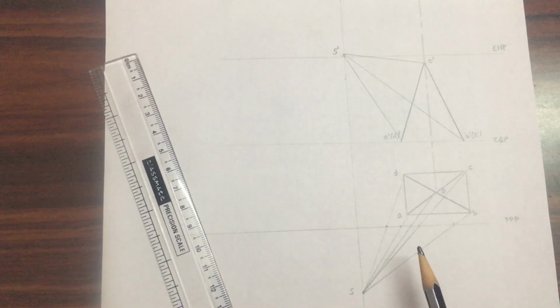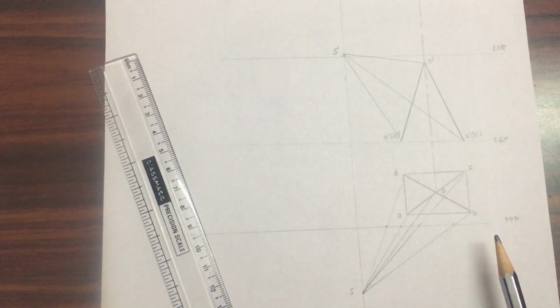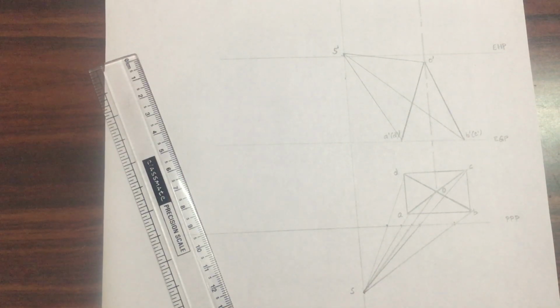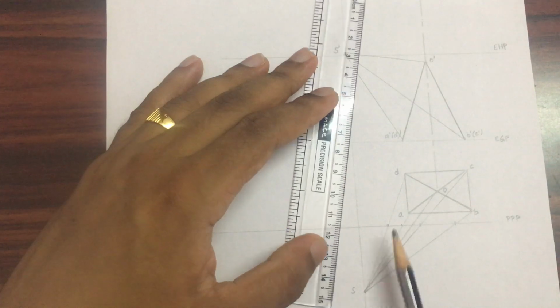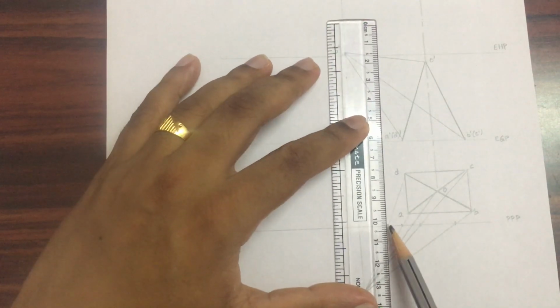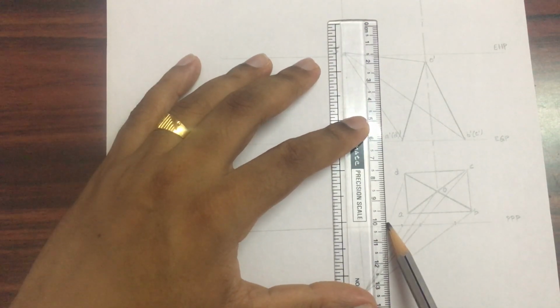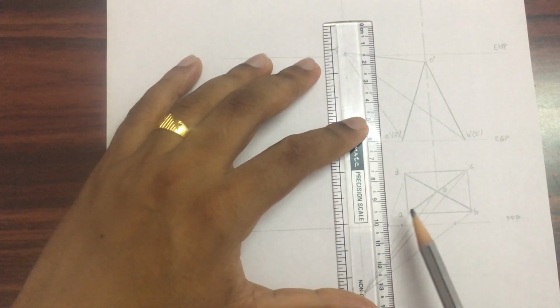These points are being marked, and after that you have to draw the projection lines. After marking these points, you have to draw the projection lines from the intersecting points. For example, this is the point on the s d line, then you have to project till s dash d dash by using thinner lines.